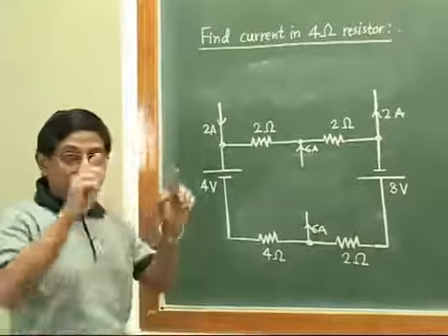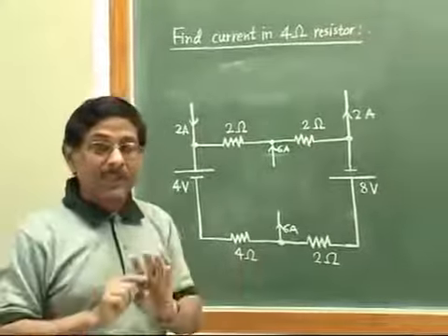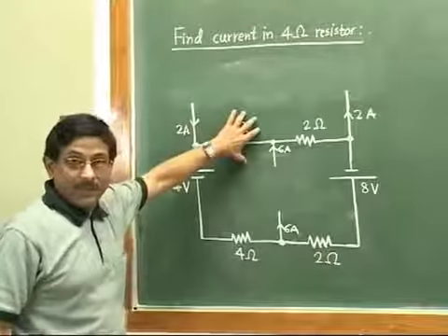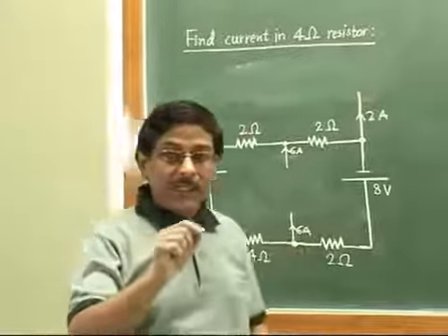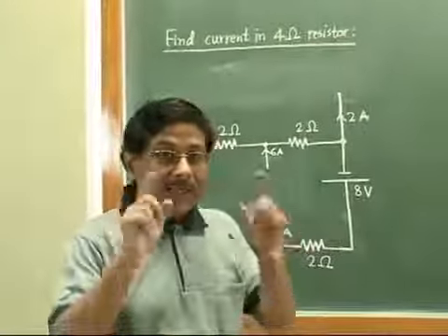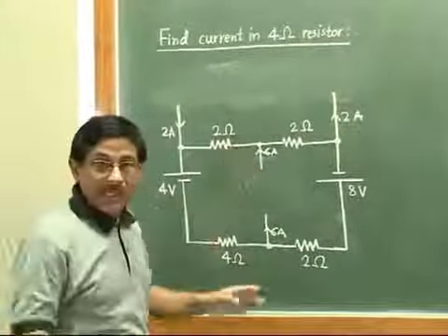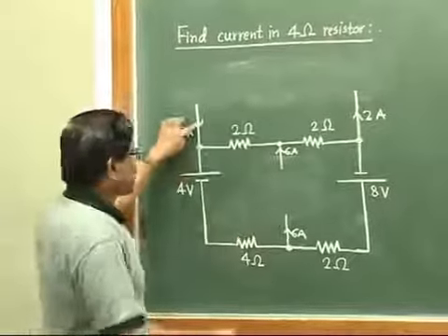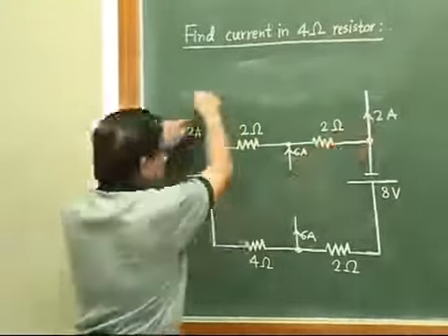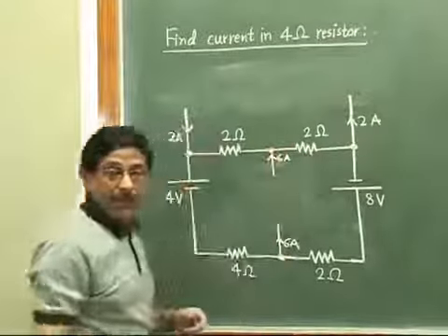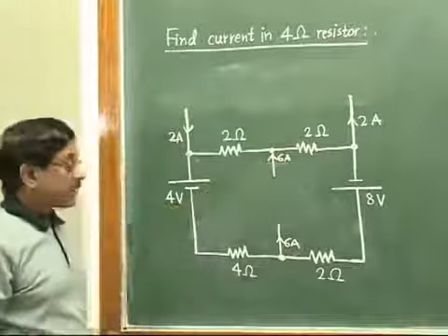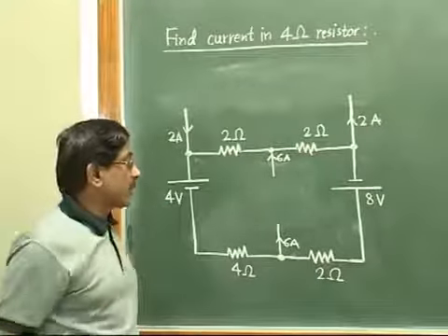So whatever circuit was given, you can replace the circuit with such a circuit. What is the idea? The idea is that you identify the branches in which current sources are there and just omit the branches from the circuit, but while omitting, you mention the supply of the current at a particular node or taking out of a current from a particular node. That we have done.